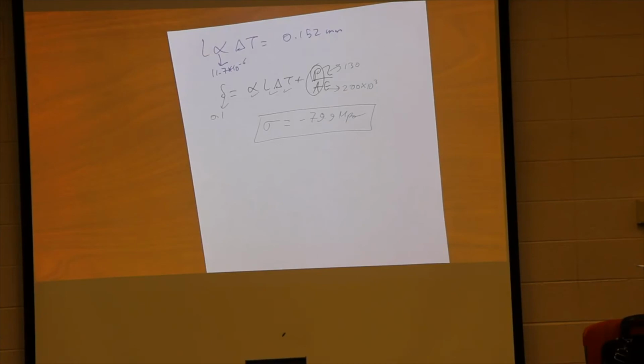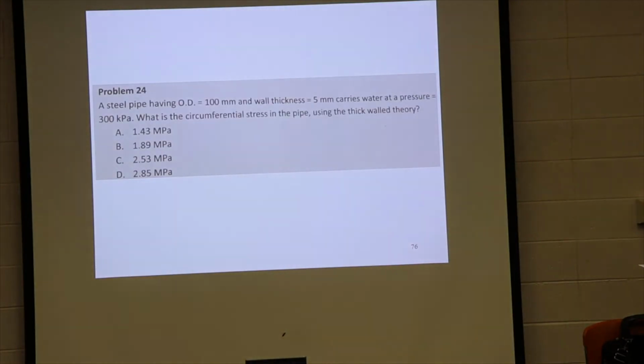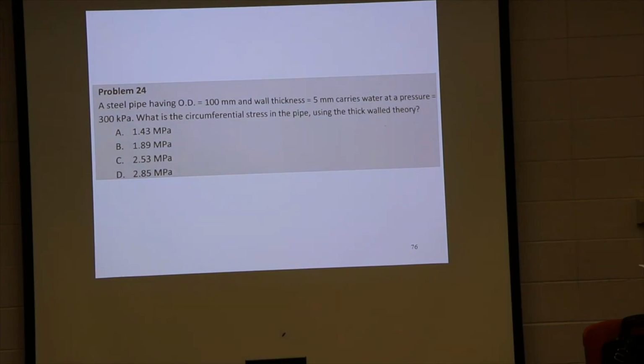As a matter of fact, since we don't teach this in strength of materials, I took the effort and Googled what the thick-wall theory is, because we don't teach it. I found that they have the solution, but I'm not supposed to explain something that I don't really know. It was found, after a tedious derivation, that sigma hoop equals P internal times R outer squared plus R inner squared over R outer squared minus R inner squared.